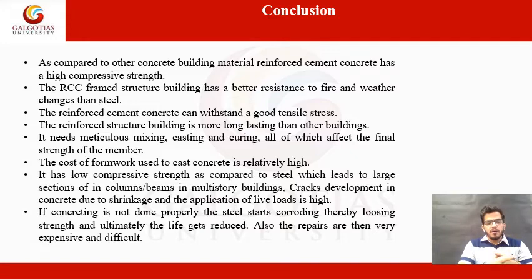If we talk about the conclusion, we have some more points regarding the RCC frame structure as the advantages and the disadvantages as well. The disadvantages can be concluded like this: it needs meticulous mixing, casting, curing, all of which affect the final strength of the member. The cost of the formwork used in cast concrete is relatively high.